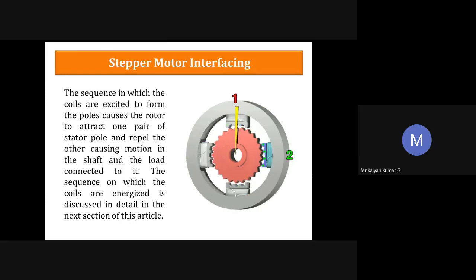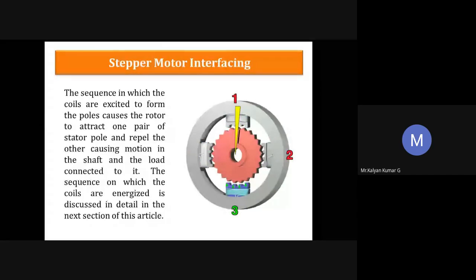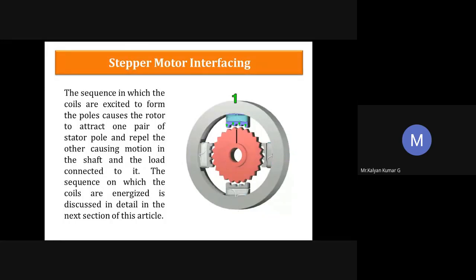If you have noticed, rotation takes place in steps, in very small incremental rotations only. That is called step rotation. And the angle to which the step rotation takes place we call the step angle, or step size basically. Clockwise, yes, very good. You can make it rotate clockwise as well as anti-clockwise. Just by reversing the electrical pulse sequence, you can make it rotate in the reverse direction.